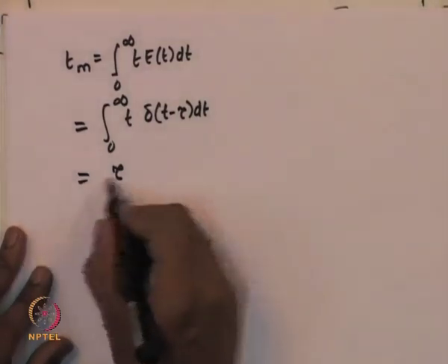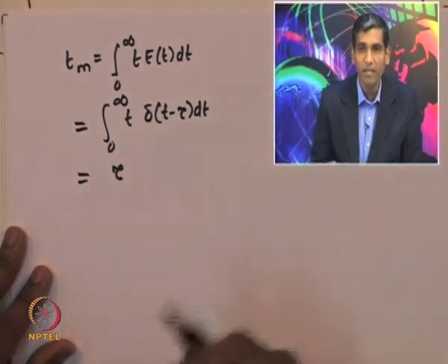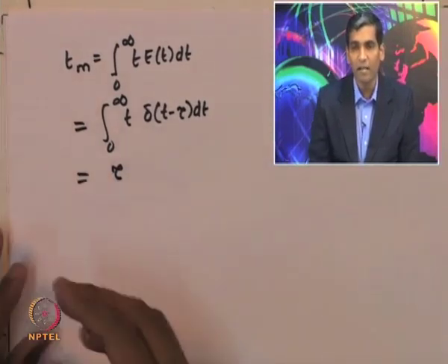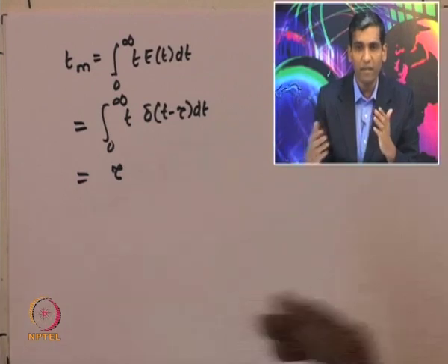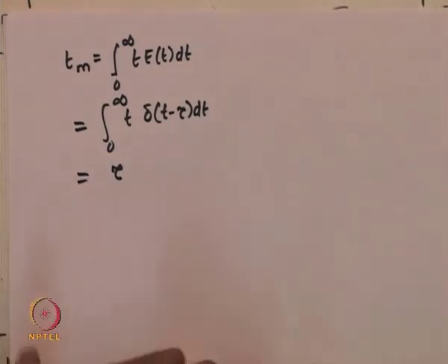So, therefore, the mean residence time is exactly equal to the space time, and this one would easily guess, because we said that an important property of the plug flow reactor is that all material entering the reactor and leaving the reactor will have exactly the same residence time, and that the E curve is going to be centered at the space time. So, the mean residence time must be exactly equal to the space time of the plug flow reactor itself, which one would guess, and it is also clearly shown by the RTD function.